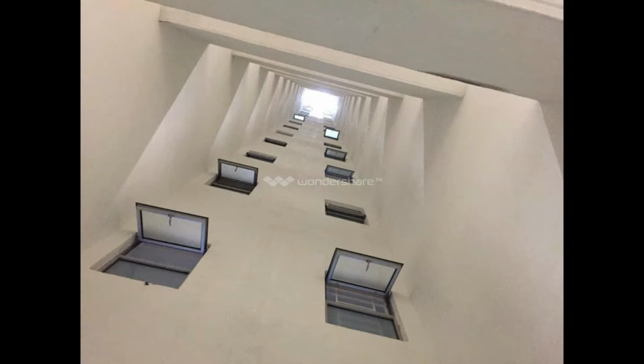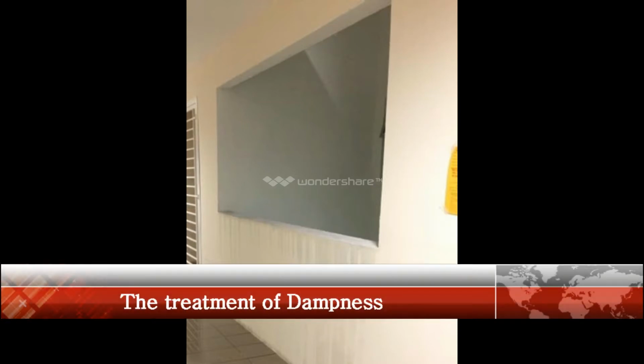Precipitation can be wind driven, so that it penetrates joints that remain watertight in normal weather conditions. In this case, treatment should start with preventing the arrival of rainwater to this area and then drying the affected area. And finally, the use of waterproofing materials for the wall.